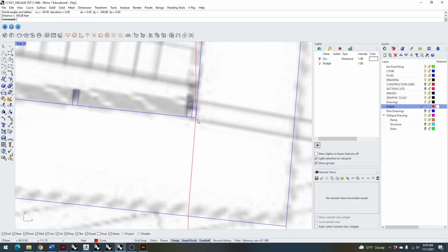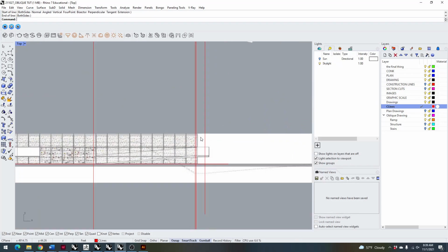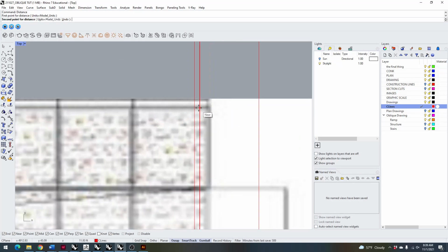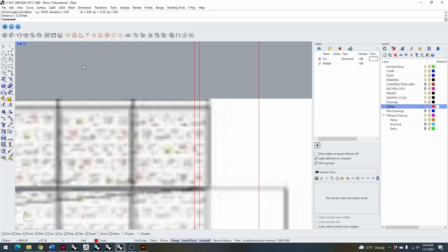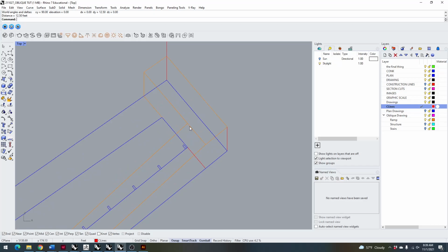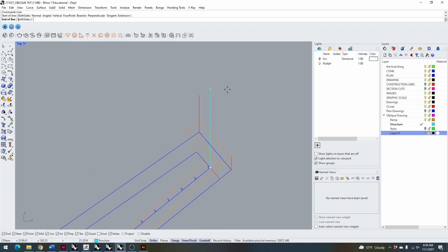So if we want to find the front corner, which is just the structure, we will find it on this elevation and find this height here, which is there, so that's 12.5 feet to the top. So we'll draw a line now in the positive Y direction, on our structure layer, positive Y up 12.5 feet.